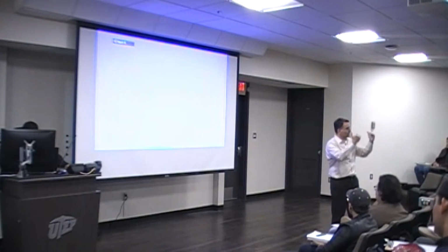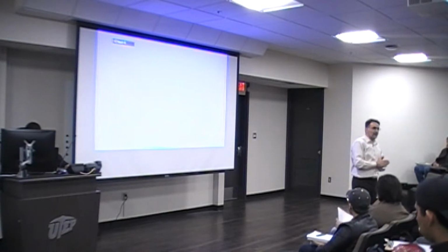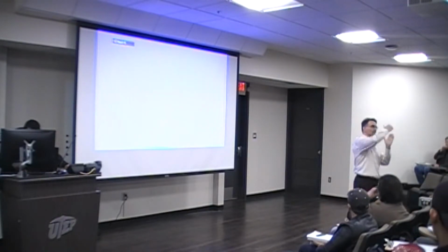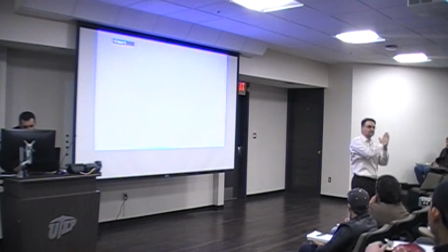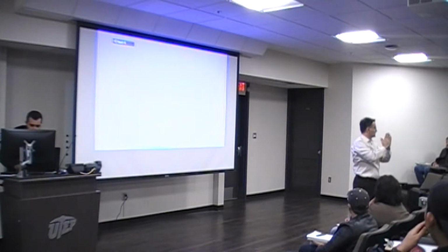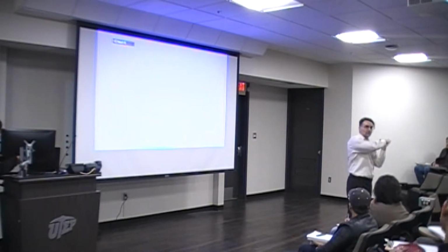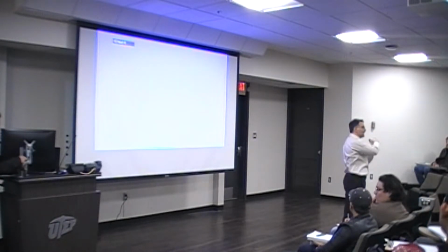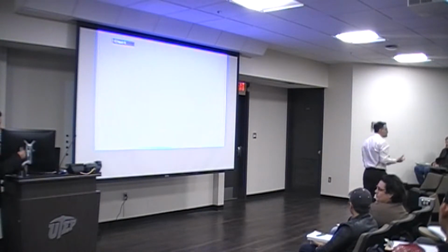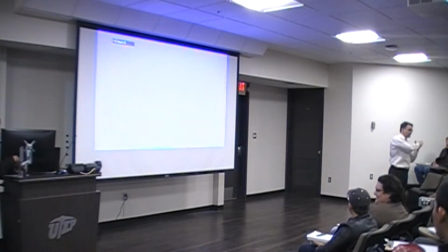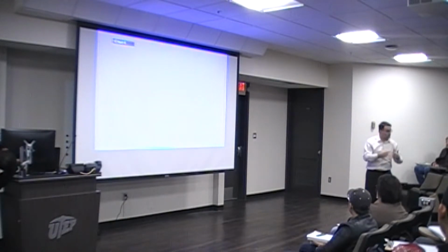So you have the load that is happening from the top. Let's assume that I have a flat and elongated particle that stays like this. What happens if you apply the compaction energy from the top? Yes, basically Margarita was showing that with her hands. For those of you who missed it, she was showing that it aligns itself with the horizontal plane. So it basically falls flat on its side. If I apply the load from the top, you basically have enough area to resist that load. But what happens if you have shear forces from the side? Basically it deforms very easily.